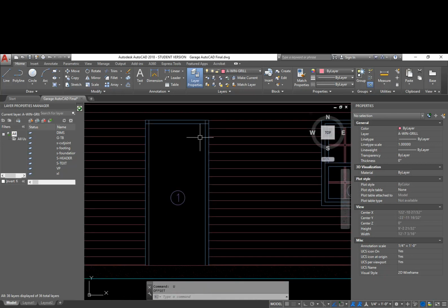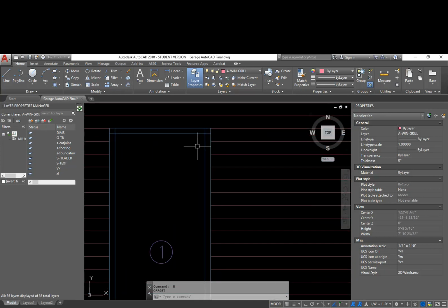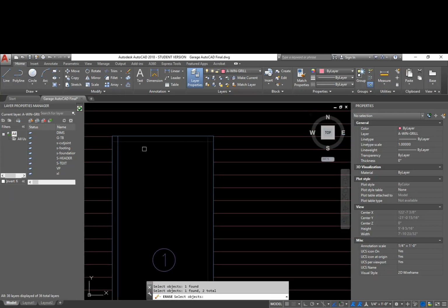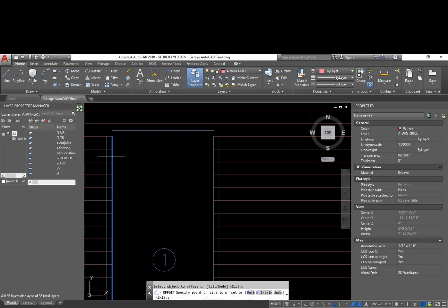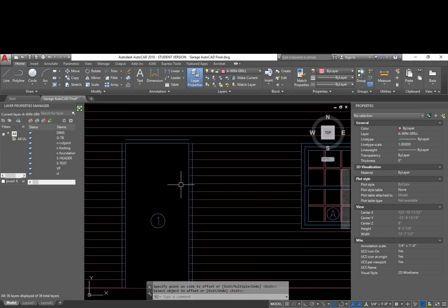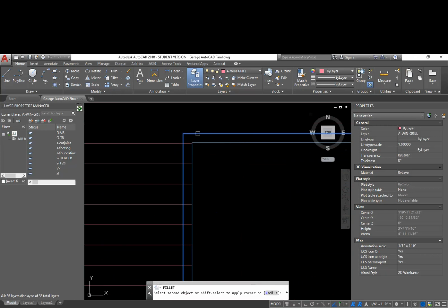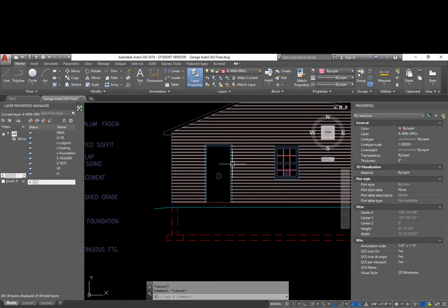Whenever I do this, I actually want to have my brick mold go outward from the door, and then I would have a door frame on the inside. So instead of offsetting that in 2 inches, I'm going to offset it out 2 inches. And if there's nothing at the bottom, just do these 3 sides. And then I would need to redo my hatch.